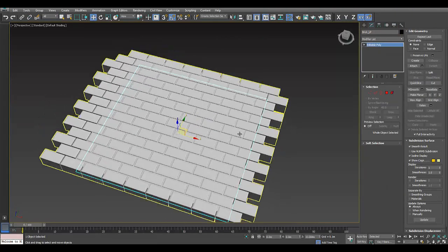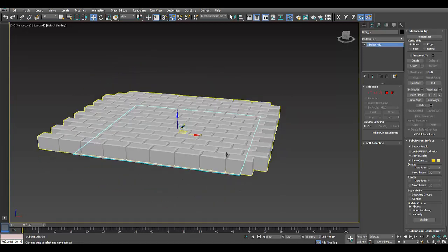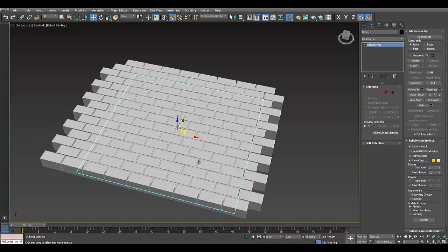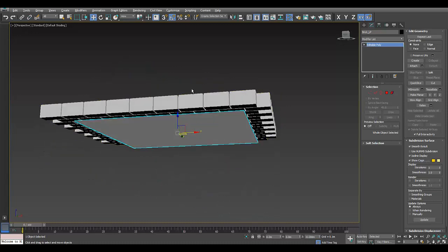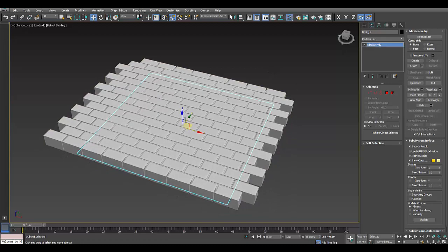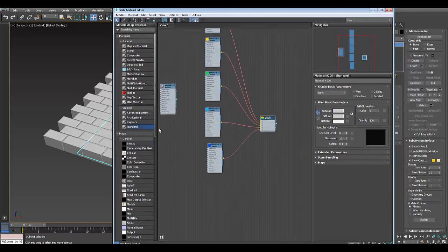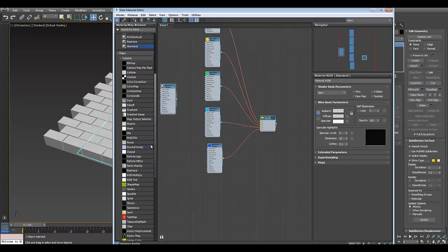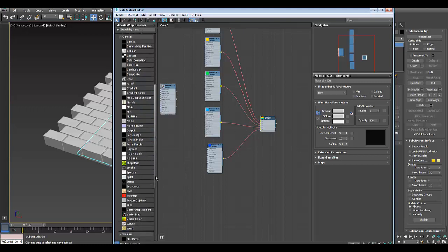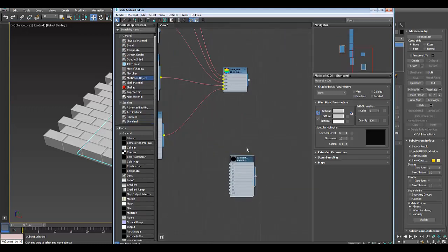Now what we want to do is tell 3ds Max I want to render the bricks onto this plane and create a sort of color selection onto that plane there. So what I would do next is, with that plane being set with UVs, I would then go into my materials. So I'll just close that in a sec and push M. I'll just bring this along. I've skipped ahead a wee bit, but essentially what I did was, in the maps area, we click for a multi-sub object. Just have a look for it. It'll be there somewhere. Yeah, so it's just up here. So I'll just drag that over here.